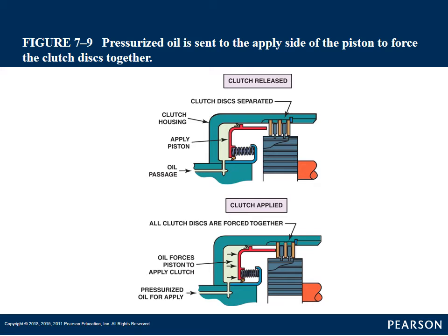This is how we get what we call slipping in a transmission, and we'll talk about that a little deeper when we get into diagnosis. It happens when for some reason these clutch packs are not holding tight together, and it could be just as simple as age, and the friction material is wearing off our fiber discs.